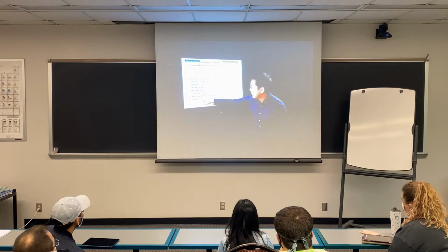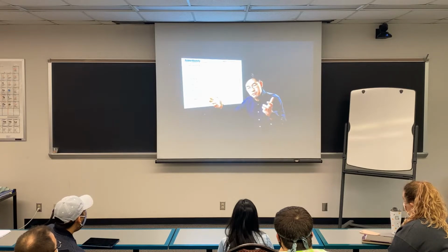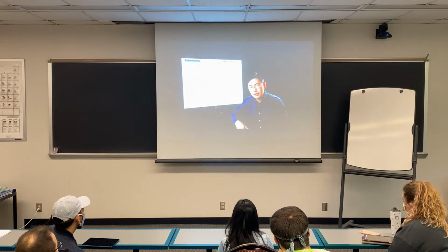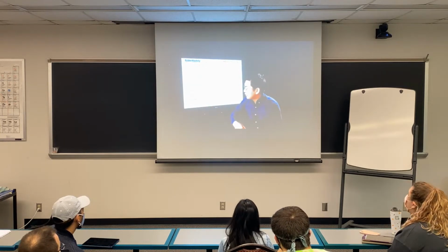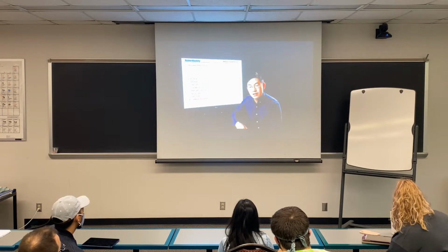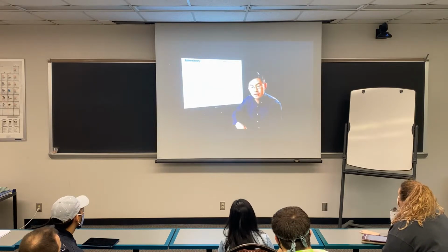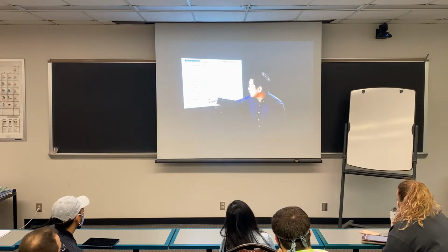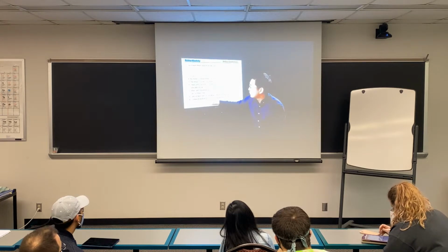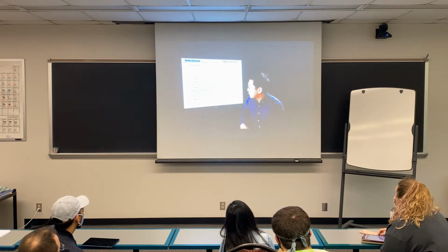Okay? And junction points affine to the macroscopic deformation. So as we talked about, when you stretch a rubber material, your crosslink points will deform macroscopically. This is not always true. Deformation is sometimes inhomogeneous on the local scale. So some points might deform slightly more than others. So this causes modification needed to understand how to address this affine deformation.